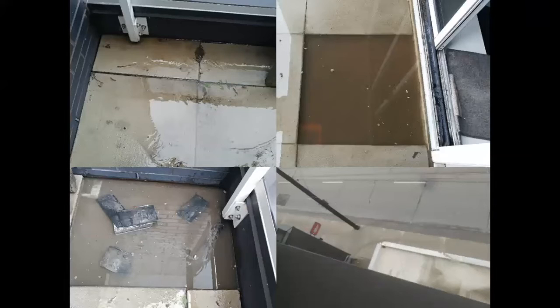Again, with heavy rainfall, you have the water ponding not only below the paving stones. When you're lifting them, you see that it's completely pulled underneath. It's coming up above the paving stones. There is potential for it to rise up over the doorway into the unit there. In this particular case, the drain was blocked with something. Once the debris and blockages were removed, you can see in the last photo on the bottom right that the water did drain off. This is one of the reasons why it is important to ensure that the drains are clear and unblocked at all times in case of situations like this.